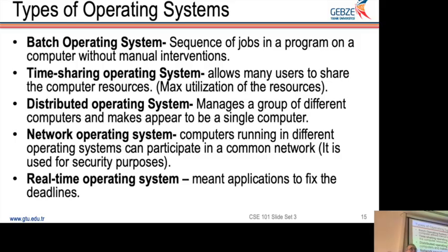With the new systems, there are electrically controlled injectors. Those injectors are opened and closed with electric pulses. And the length of those pulses determines how much fuel you give to the engine. You have to compute that amount 60 times a second, before anything happens, before it occurs. If you are late, the engine keeps rotating, so there will be a misfire. The engine will stall.